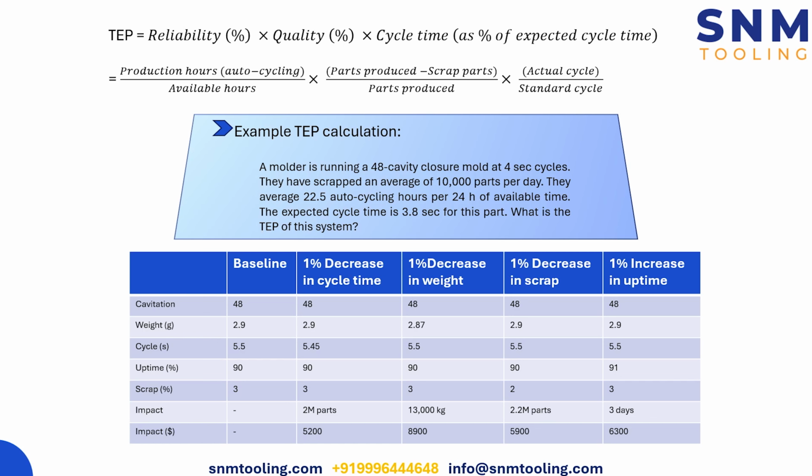The second scenario is, even if the mold makes good quality parts at a small frequency, meaning at a larger cycle time, that mold also is not optimal, because the parts frequency is less and the other consumables are more, which is why the net productivity is less.